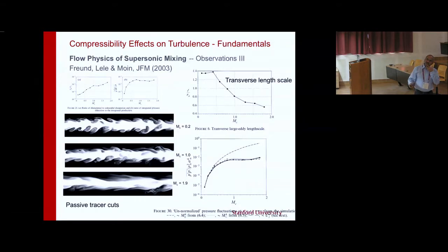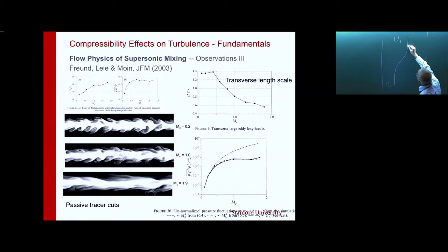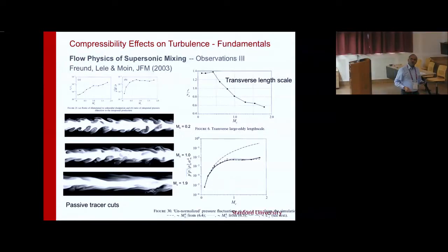And so if we think about how intense pressure fluctuations are as a function of convective Mach number, you can make an estimate for pressure fluctuation by thinking about, if we say that there was active overturning on full scale, the scale delta, then based on the velocity difference between the two streams, you could say that there is a dynamic head associated with that velocity difference, and pressure should scale with that if the density was more or less constant across the flow. And that would be this estimate, this dashed line that is going up, and that's a way overestimate. Pressure does not scale anything like the dynamic head. It's much less.